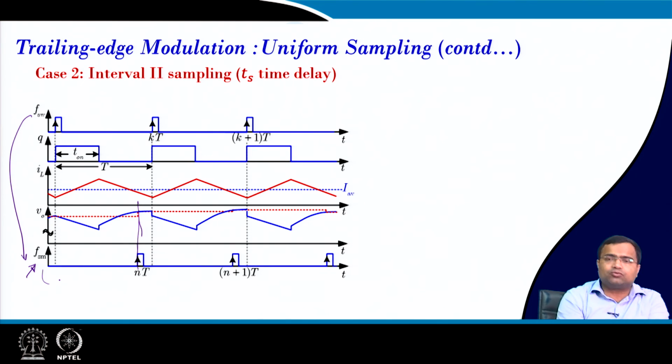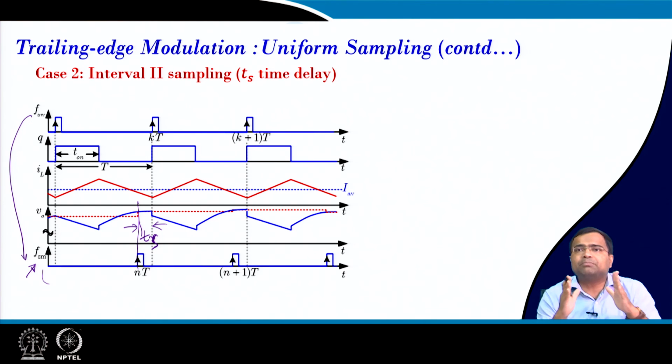So this clock will be sent to your A to D converter, and then after this delay time, this is a TS delay time, it should complete both the conversion of the ADC as well as the computational time. That's why we have to vary the delay based on what sampling rate you are using and what the conversion time is, and the conversion time of the ADC also varies based on the architecture of the ADC. If you are using a pipeline ADC, then the conversion time depends on the number of pipeline cycles. If you are using a flash ADC, it is very simple, but it is rarely used in commercial products because of a high resource cost.